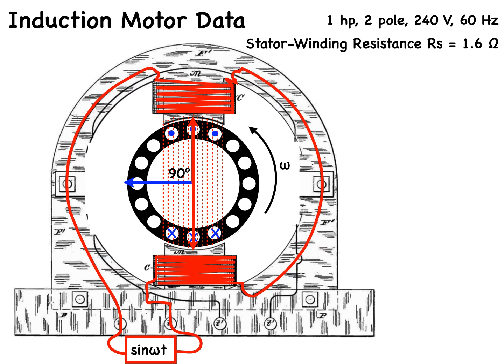The no-load test results are, with an applied no-load voltage, VNL, of 240 volts, which supplies a no-load current, INL, equal to 3.8 amps, and draws a no-load power, PNL, of 190 watts.